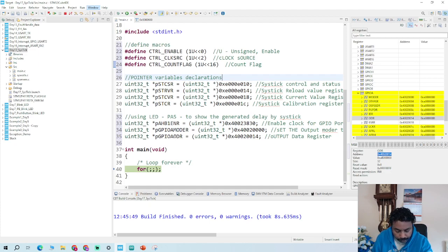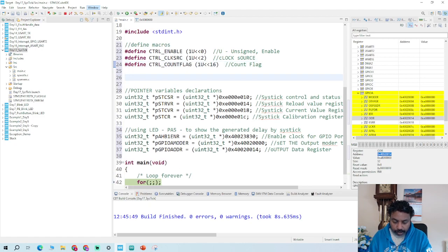Okay, so we have written the enabled values. So now the next one is, you need to define the sysclock. As define sysclock, we're going to use 16 megahertz. So SysTick load value is, we're generating a 1 millisecond delay, and that's the reload value. The value is 16,000 as you calculated in that formula, so you got to define that there.